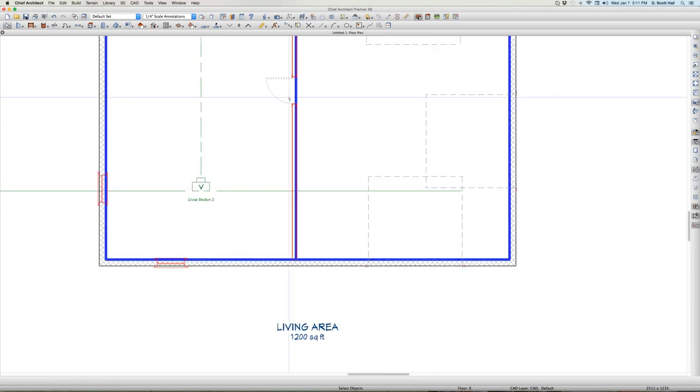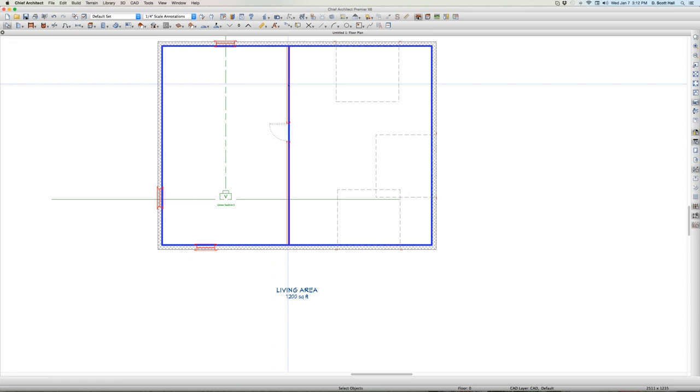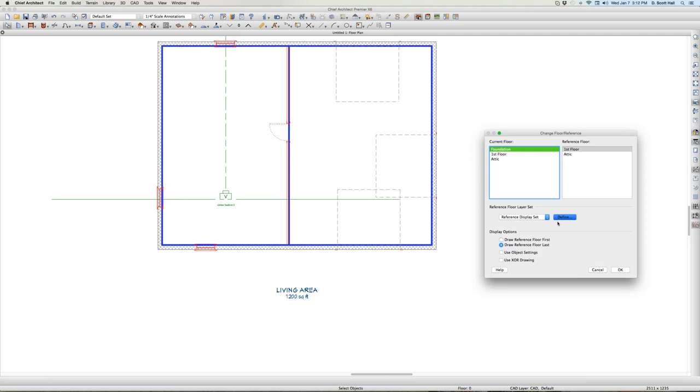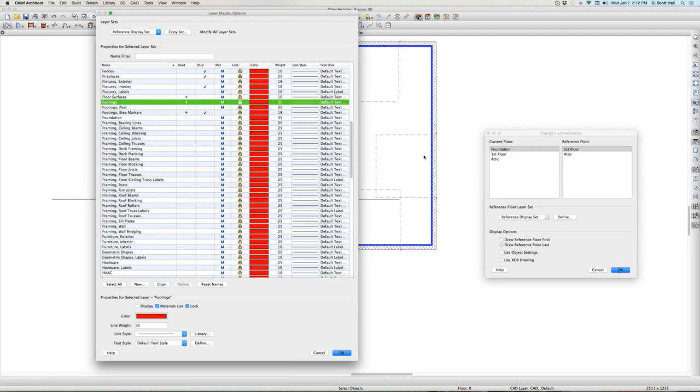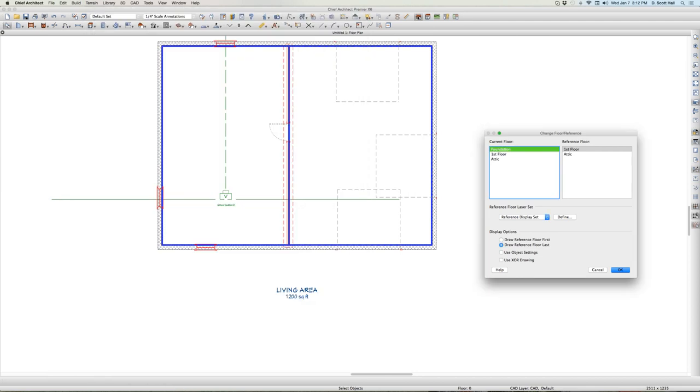Oh, look at this. I'm in a different annotation set. Remember, I had the walls set up correctly. Anyway, bottom line. We'll come up here. I'm going to turn on my footings, okay? Turn on my footings. Reference layers. I don't know what happened. If you have your stuff set up right, you'll know what's going on. All I'm doing is I'm using the reference layer set to show the...